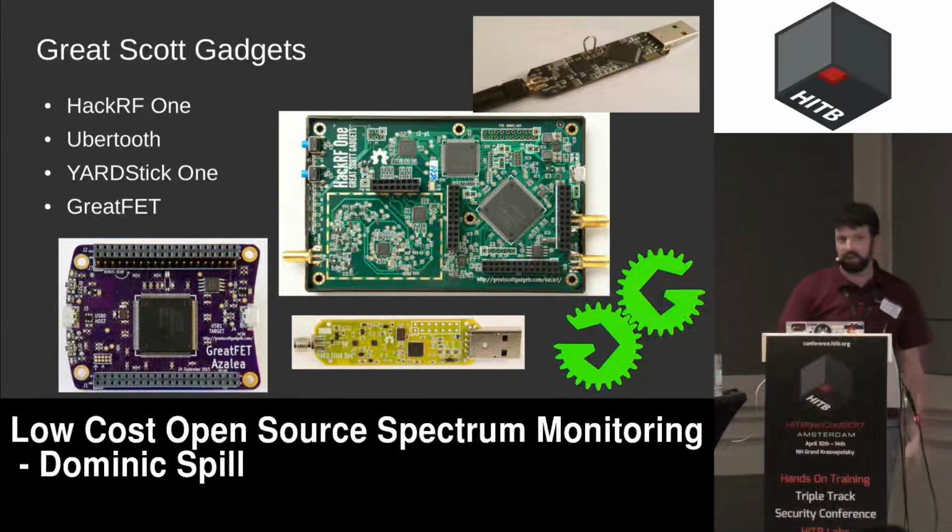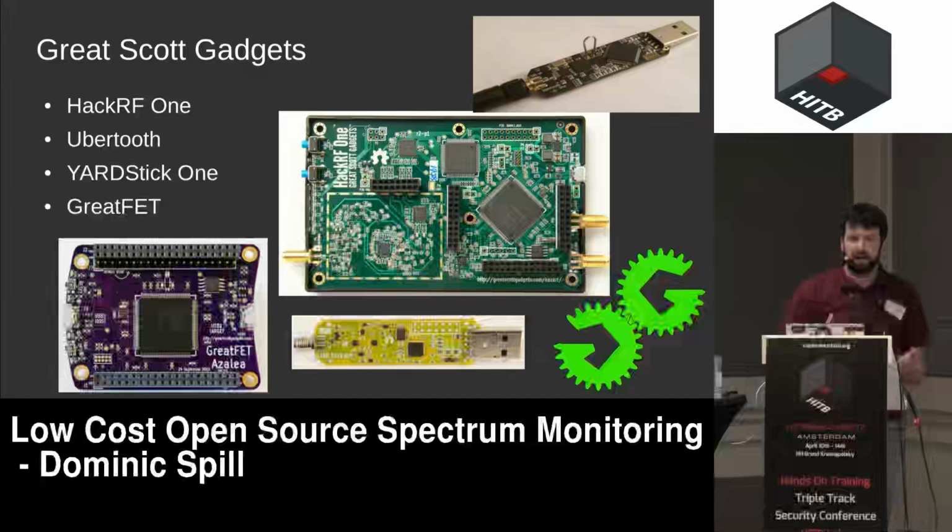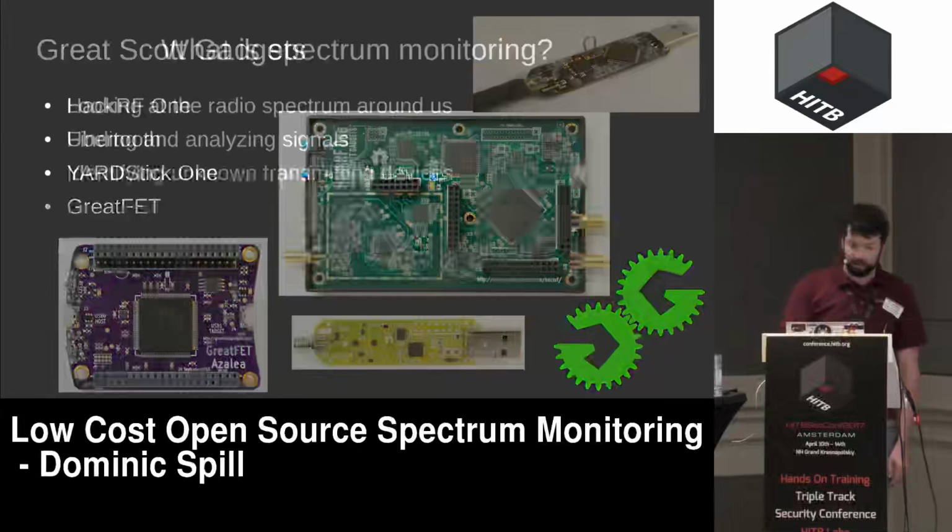It's a software-defined radio. It has a 1 megahertz to 6 gigahertz tuning range. It grabs 20 megahertz of bandwidth, and it's all open source, including the hardware and the firmware. And what we're going to do here is we've written some custom firmware to do some interesting things that you can go and play with.